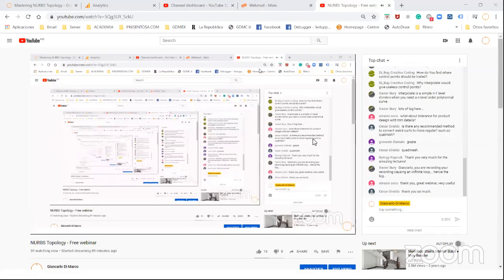Drawing directly on the surface gives me a little control over the shape of the curve along the surface. If you project it, you have more control on the planar aspect of the curve, and then projection deforms the curve according to the surface, but the final curve will always lie on the surface within the document absolute tolerance. So it's not more precise.